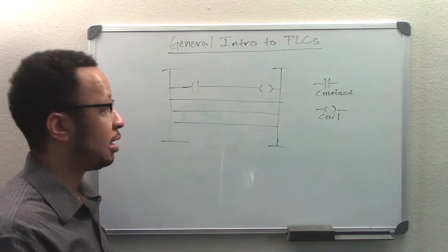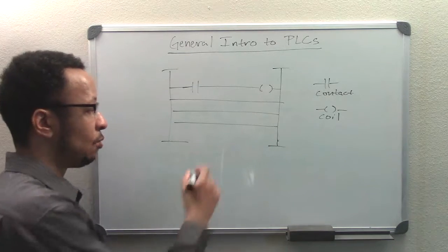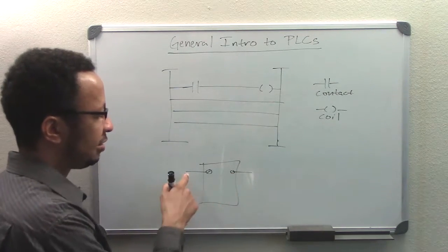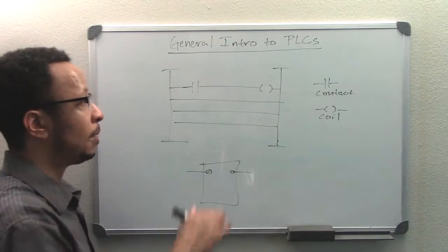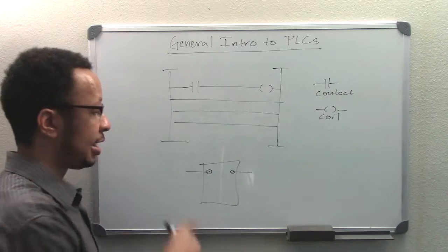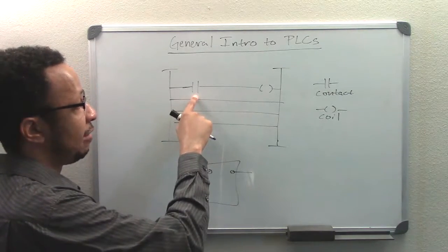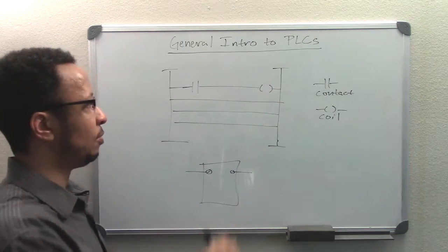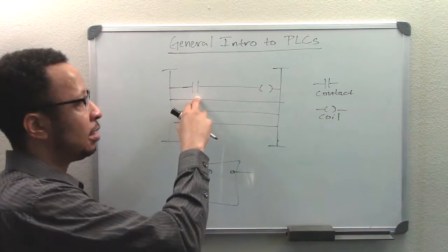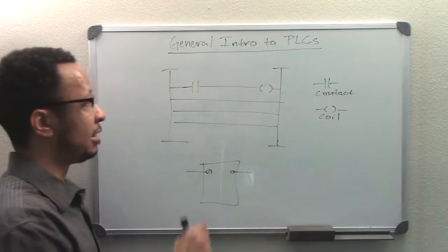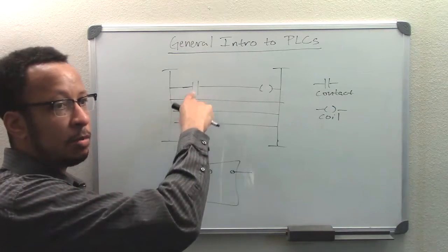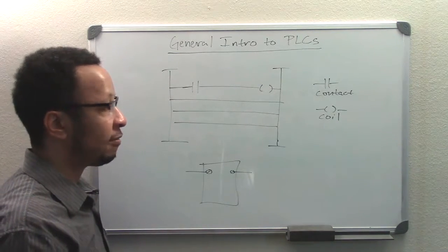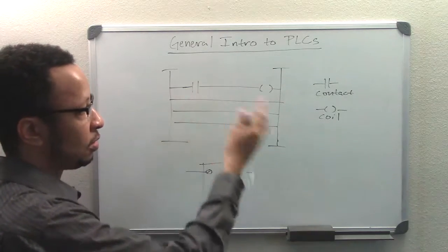Now the difference between that is that contacts can be wired to, say, like this is your PLC again. Contacts can be wired to inputs on your PLC. And so if I pressed a button that energized this terminal on the PLC, now I would have a closed contact. In the PLC program, it doesn't actually animate it and close it, but it will animate it by highlighting it, so you'll know that it's closed because you see that it's highlighted. It either illuminates to be maybe green or some other color, or it's not illuminated, like an on or off condition. And so that's the animation that they offer you in these programs.